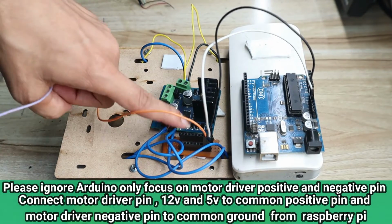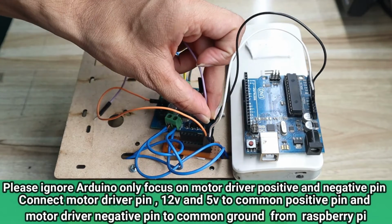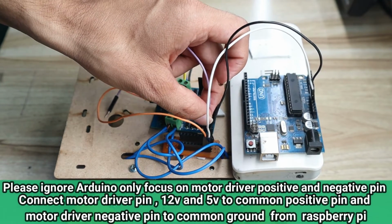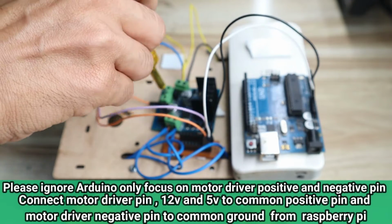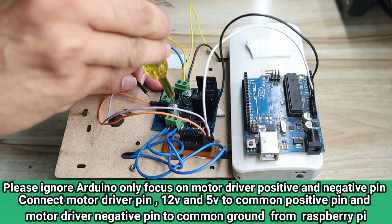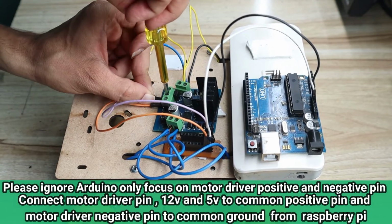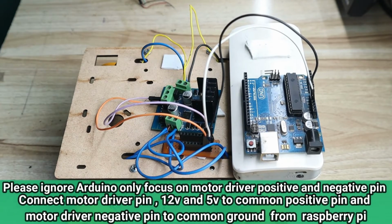Take the negative pin from this common supply, that is the ground pin, and connect that ground pin to the common ground. Okay, that common ground is the ground for this L293D IC, that is the middle pin. Okay, this is the very basic part you have to do.